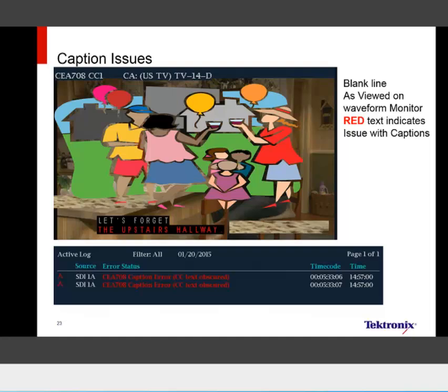You look at an SDI monitor, and unfortunately, 3/4 of the SDI monitors will also always show white fonts. They will not show you the black line. So your SDI monitors will be lying to you in most cases, not telling you that you actually have a legitimate issue that's going to cause customer complaints.